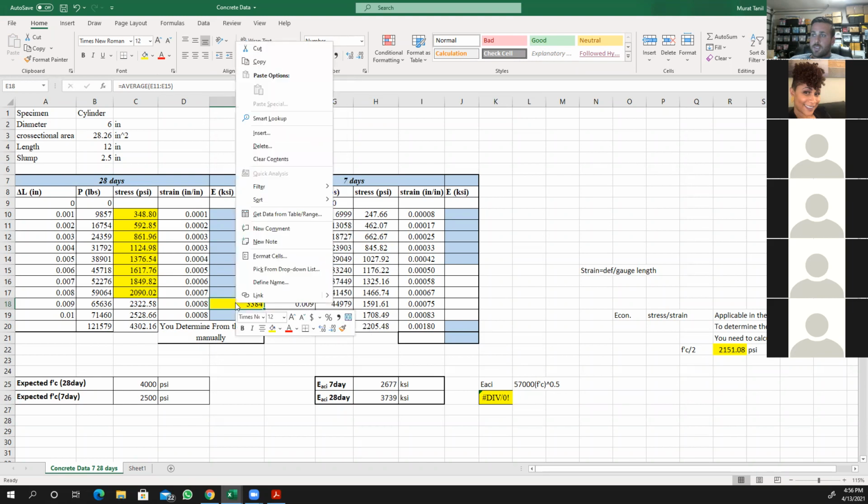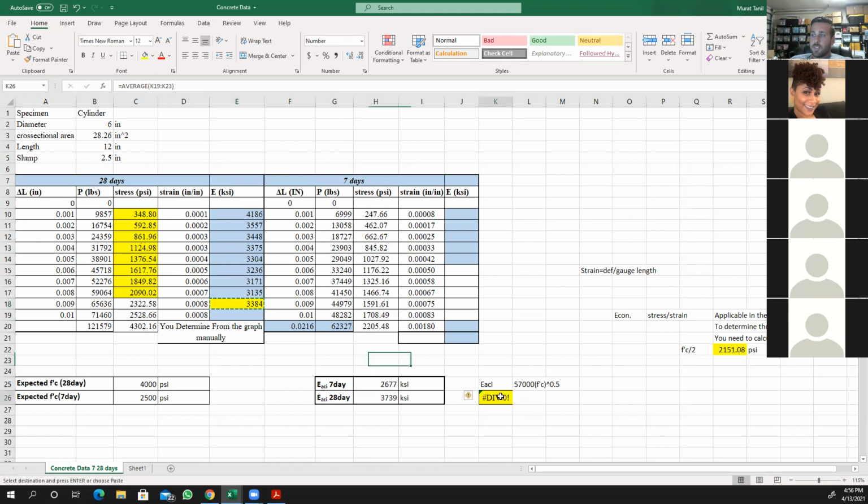And the reason for that, this is the real test, and we only tested one specimen instead of testing multiple specimens and getting the average. Imagine you test more than 100 samples with the same mixing conditions, the same curing conditions, the same temperature during curing, and the same humidity. And you use the same cement water ratio, then you should expect the same maximum compressive strength at the end of 28 days for each sample. But it is not the case.